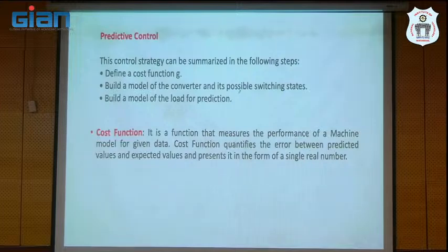Which voltage vector is working effectively in the next sample period, we can predict by taking the cost function. The cost function contains the errors of the target variables. What are the target variables for an electric drive? Torque error, and our target variables are torque and flux. In the cost function, there are two.